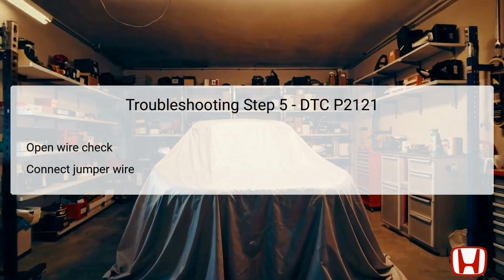If there is continuity, this validates that the APS1 wire is in good condition. If no continuity is found, an open in the APS1 wire exists between the PCM and the APP sensor, necessitating repairs to restore proper electrical connections. In step 6, you'll check the internal circuitry of the PCM.